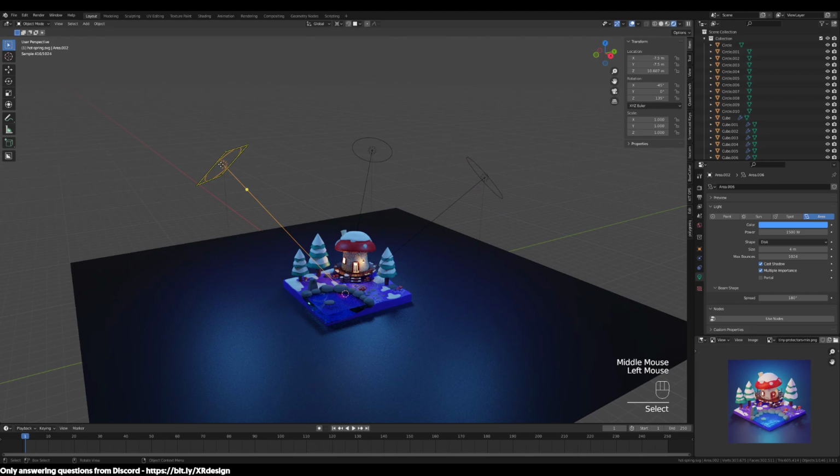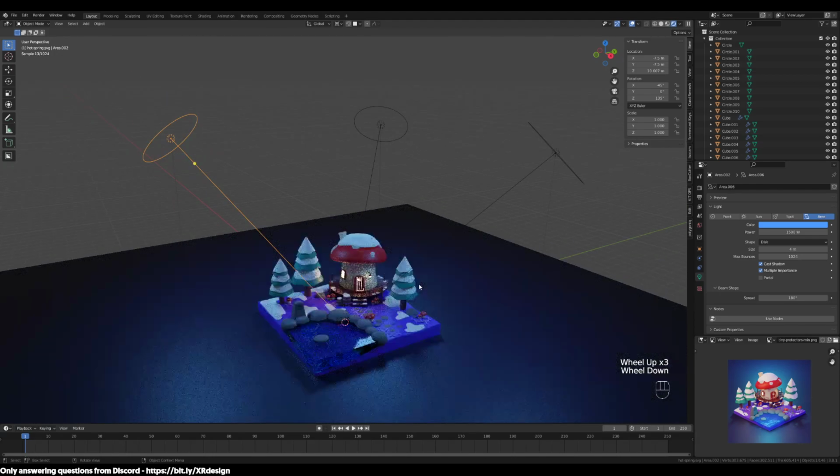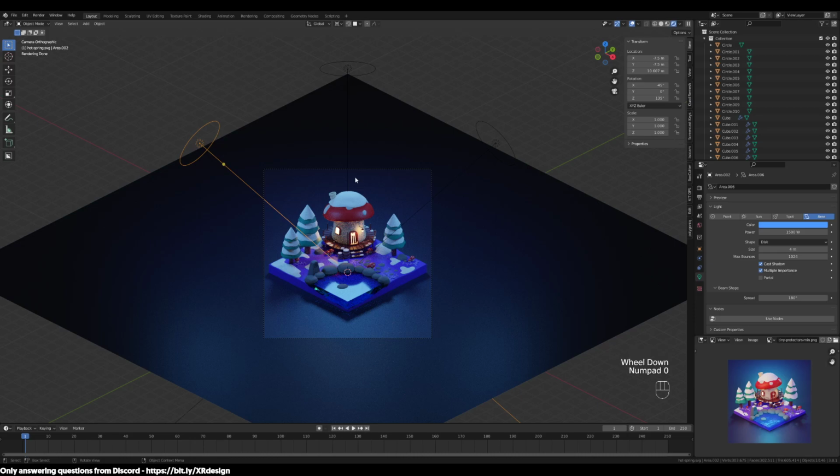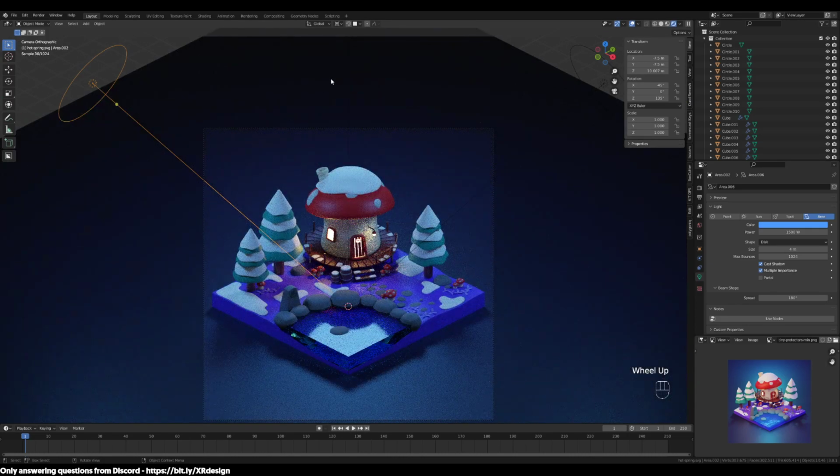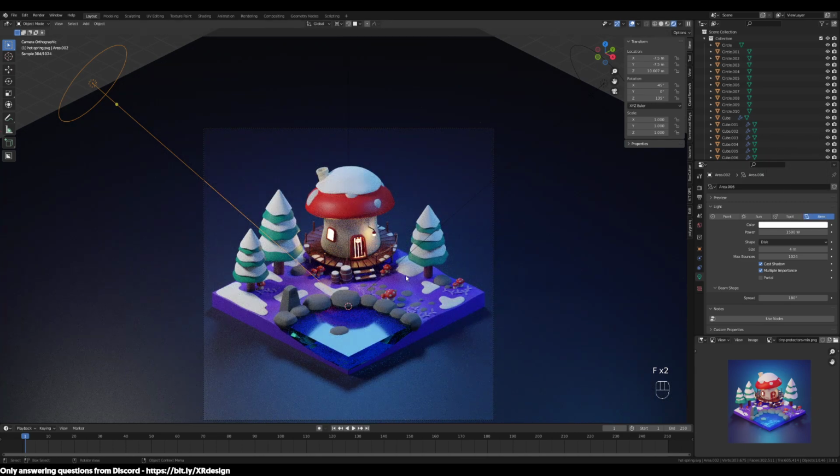This way I found that if you have three light sources, it lights up the scene evenly. If you had just one sunlight, that works too, but I found that you have more flexibility if you have multiple light sources lighting up the scene. And then for the left one here, make sure you select it. We're gonna change that to white. So I'm just gonna change it to FFFF. Immediately it becomes a bit brighter. And I'm gonna change this to 750.